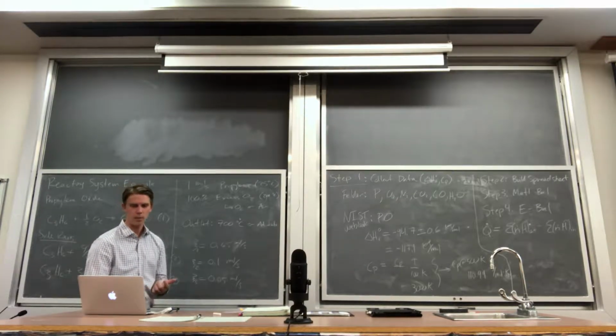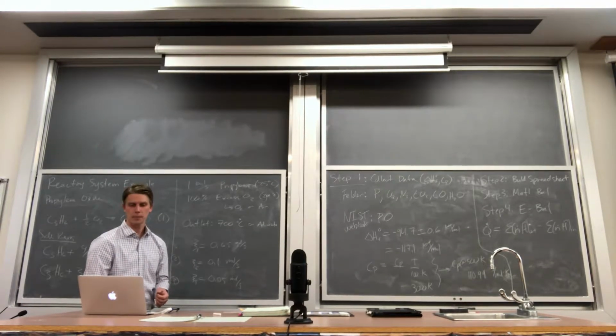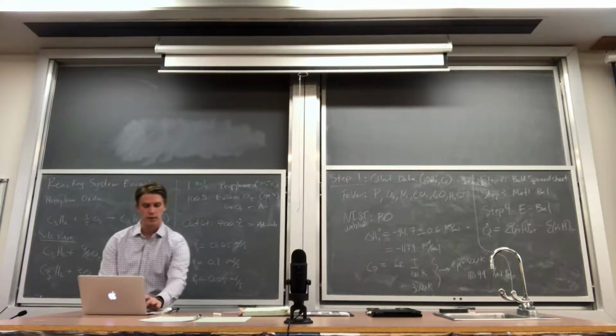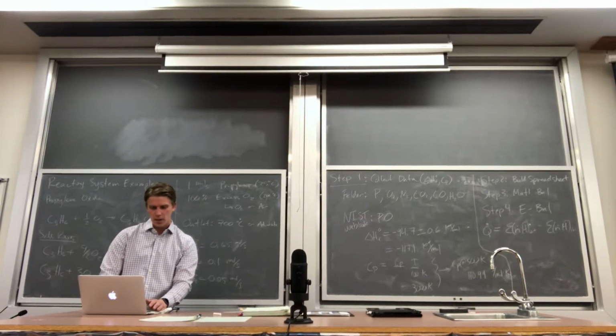If I wanted to be a little bit more elaborate, I could change this to an actual stoichiometric coefficient term. But basically, I'm adding in the 100% excess. And for inputs, I have nothing else going on here. And then for the nitrogen, this is my little clever formula where it goes to 0 if it's pure oxygen, basically by just multiplying it by either 1 to change nothing or 0 to get rid of everything. Simple enough. Now, this next column here is for the mole fractions.